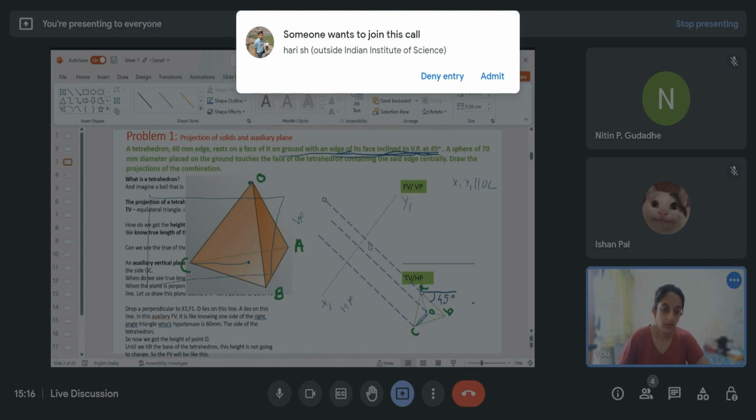So now in this plane which is parallel to OC, initially my vertical plane was like this, my horizontal plane was like this, my vertical plane has now become like this. So will the projection of the height of this O change? No, it will not change in the vertical plane. What has changed is it's equivalent to rotating this top view. Instead of taking this one and rotating it, I've just placed a plane x1 y1 which is rotated.